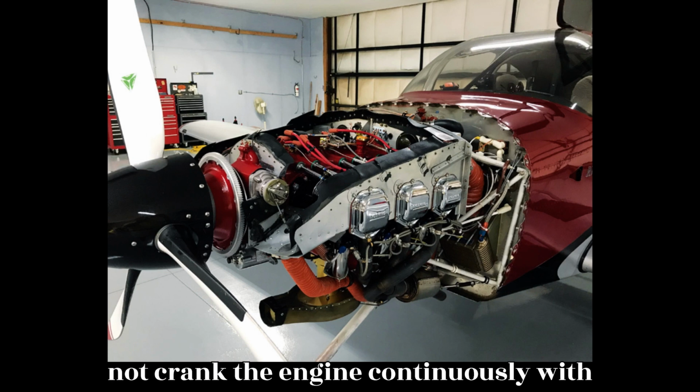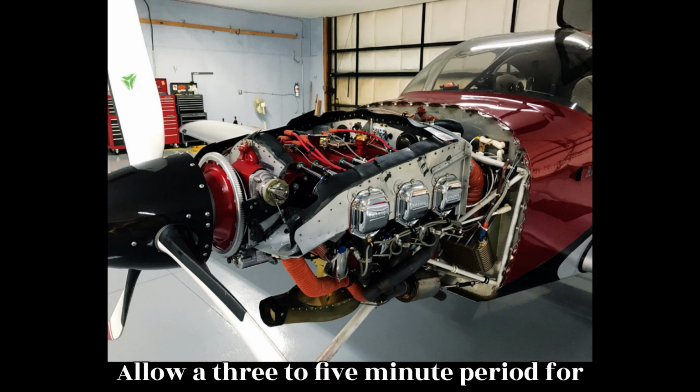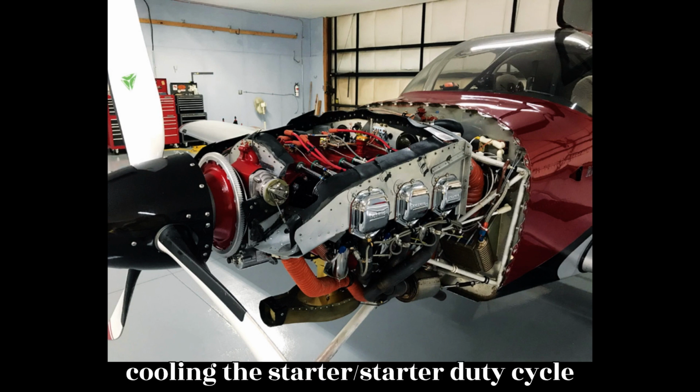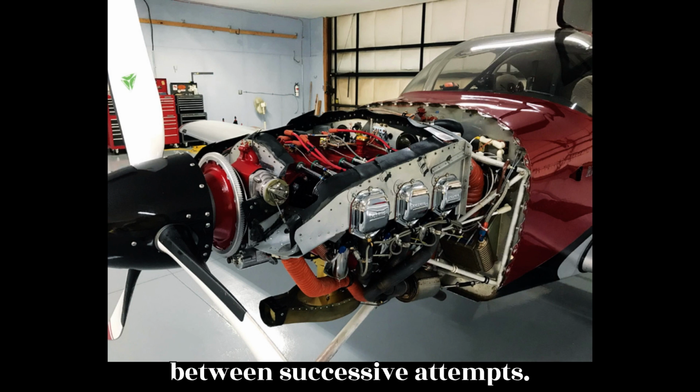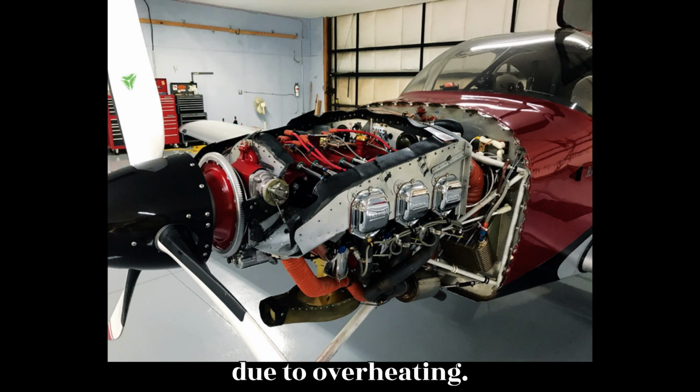Do not crank the engine continuously with the starter for more than 1 minute. Allow a 3 to 5 minute period for cooling the starter duty cycle between successive attempts. Otherwise, the starter may be burned out due to overheating.